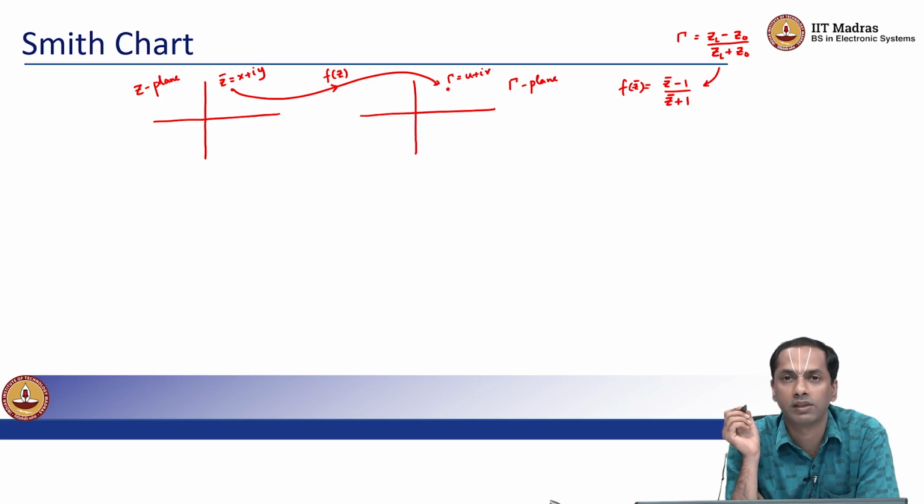The reason to do this is so the chart is independent of the characteristic impedance. So we know automatically that if you are showing me a Smith chart in the gamma plane, you have normalized all the impedances to the characteristic impedance of the lossless transmission line.